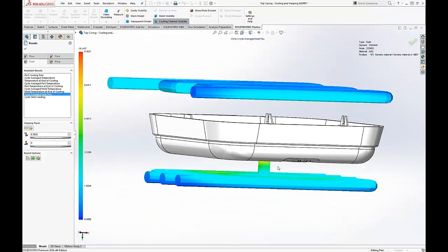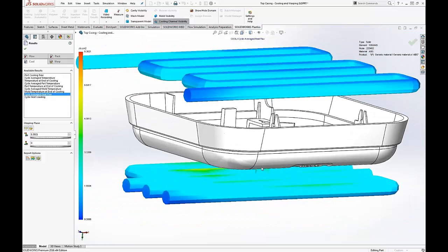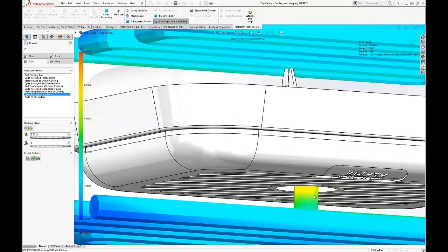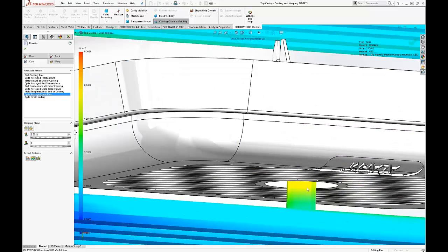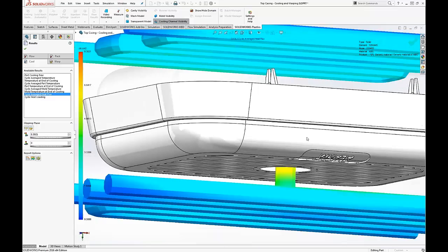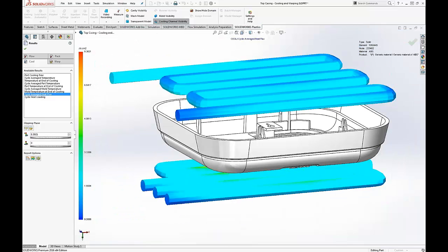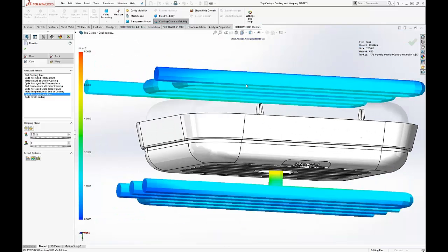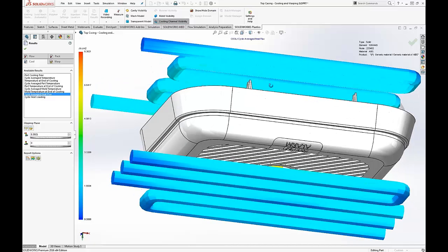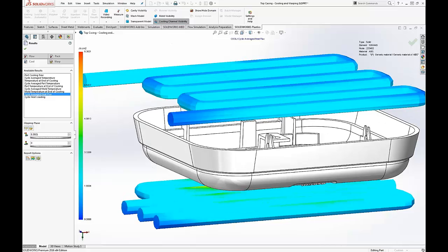So it's a matter of measuring the efficiency of the cooling system. There are far more joules, of course, from the baffle, because it's inside, very near to the cavity, instead of those cooling channels here. And maybe you can optimize the dimension. Maybe 10 millimeters is not needed, you can try with 8.